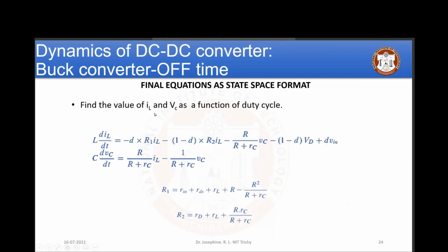So now I want to find the value of IL and Vc as a function of duty cycle. As you can see, dIL by dt and dVc by dt, I have obtained these equations. So these are my state space equations. So let us see that in simulations.